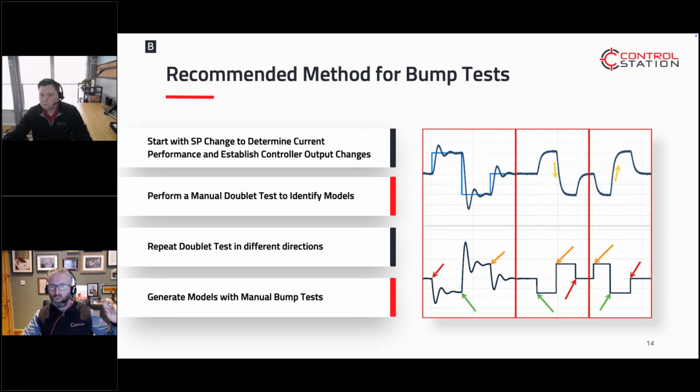The negotiation, one thing I would say to the set point is really good at the start of a process if you don't know the process. But I say look back on the trend a week, a month, a year to see where this process lives. It lives between this range of operation. So you'll get a high degree of confidence as to where this process operates, and then you can design your step test to go through it.